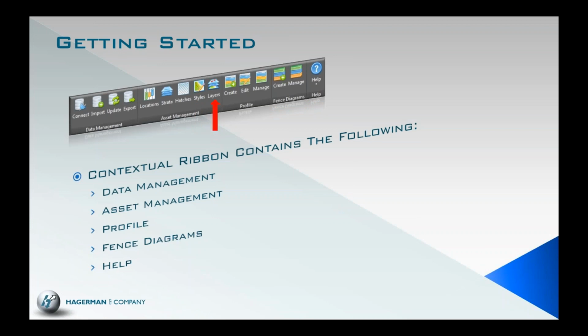Okay, separate from our Civil 3D / AutoCAD Layer Manager. What this is used for is to define the naming convention for our layers being used. You can add a prefix and or a suffix with your drop-down options, so we can display our objects, our stratum, and our elements properly or to our satisfaction.